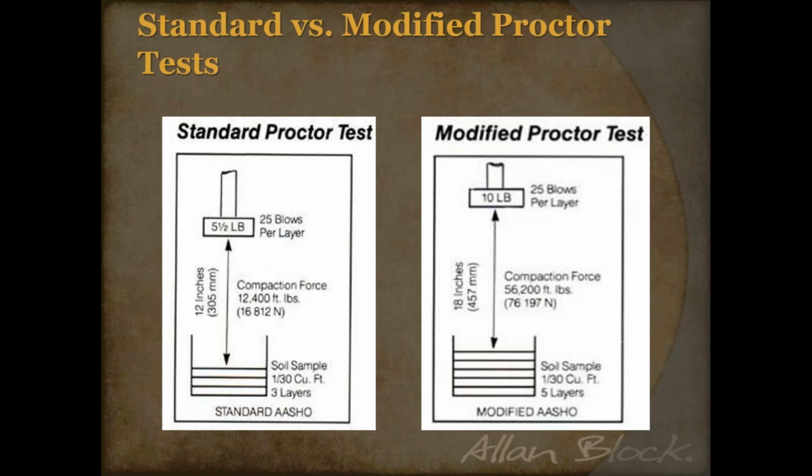And it is interesting. I notice modified versus standard Proctor, there's a lot of debate. Some of it's regional, really specifically here in the U.S., the western side of the U.S., especially up and down the west coast, where you have the seismic zones. Modified tends to be more used, but standard is Midwest and East, where we don't have those same dynamic loadings. But modified, anytime I've got a loading or surcharge roadways, that kind of stuff, I tend to look at that way.